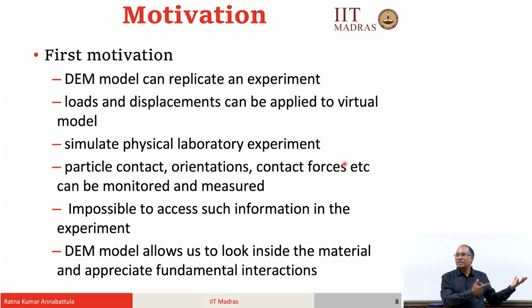So, by using the discrete element method, because it is a numerical technique, although you are compressing and measuring the macroscopic response, you also have access to what is happening at the particle level. That is one of the USPs of the method. As I said, it is impossible to access such information in an experiment, and DEM models allow us to look inside the material. When I say inside a granular system, you can actually sit on one of the particles and see what is happening, right. That is the meaning of running a granular material simulation.